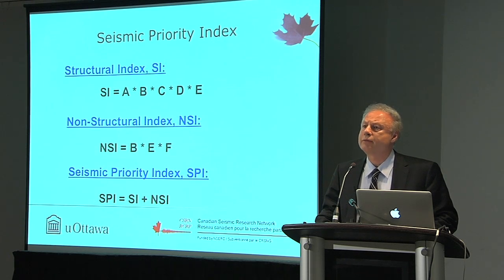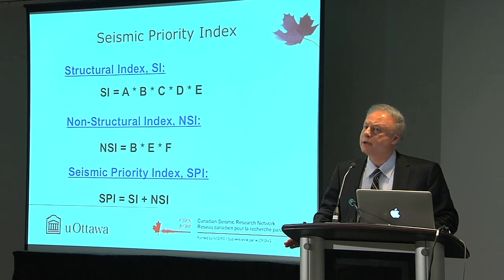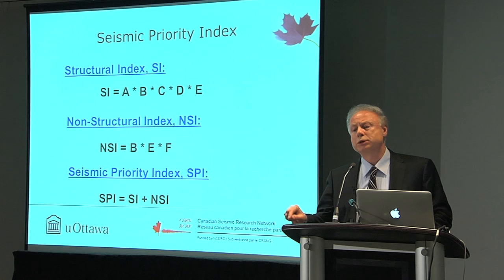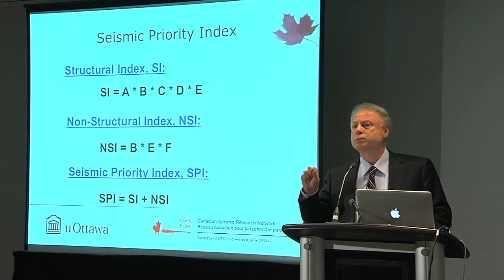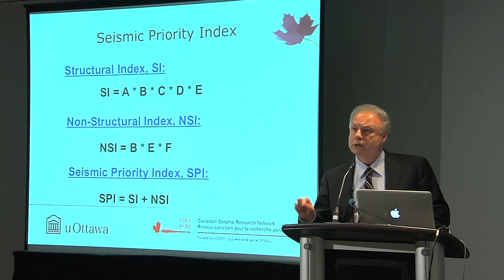Some buildings have inelastic capacity, the ability to absorb seismic-induced energy without failure, and these buildings would certainly be looked upon as favorable buildings, and this is the coefficient that reflects the differences between a well-designed reinforced concrete structure and a poorly, not even designed, non-engineered, unreinforced masonry construction. So this is where factor C comes into the picture.